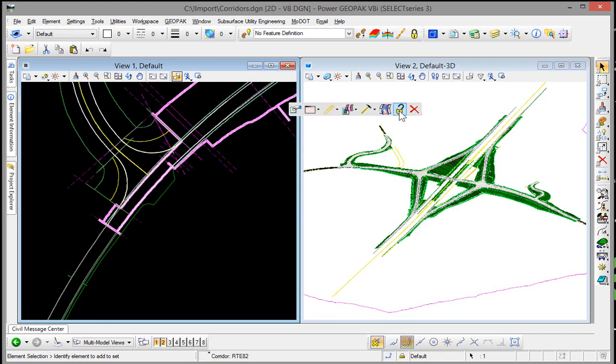And then after that lock is turned back on, the next command that is done to that corridor will force that change plus all the other changes that essentially queued up into memory to be processed. And so the rule lock and unlock activation is a very powerful way to hold off any processing until you have all of the changes incorporated that you want to make. Then you can activate your rule, and that will in turn process the corridor. Every corridor will have its own activate and deactivate option.